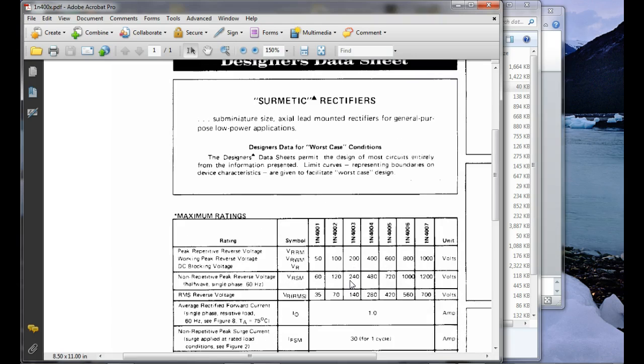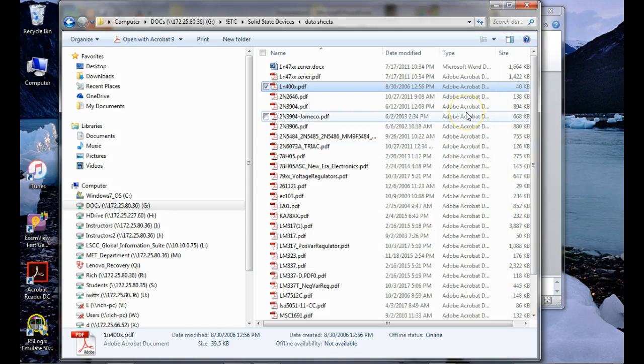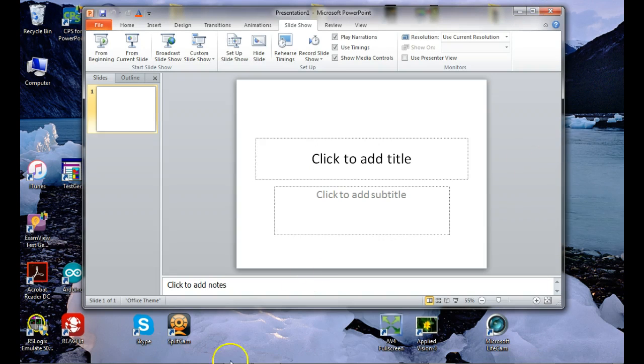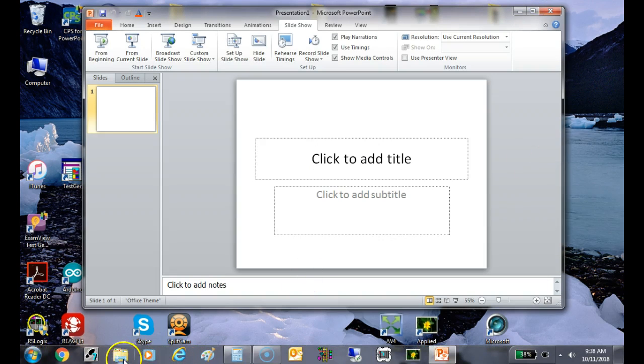And transistors have the same rating, but they call it something a little different. Since they have P-N junctions, if we reverse bias it and exceed the breakover voltage, it's going to avalanche and be destroyed, if we don't protect it with something. Okay, any more? Let me make that correction right now while I'm thinking about it.